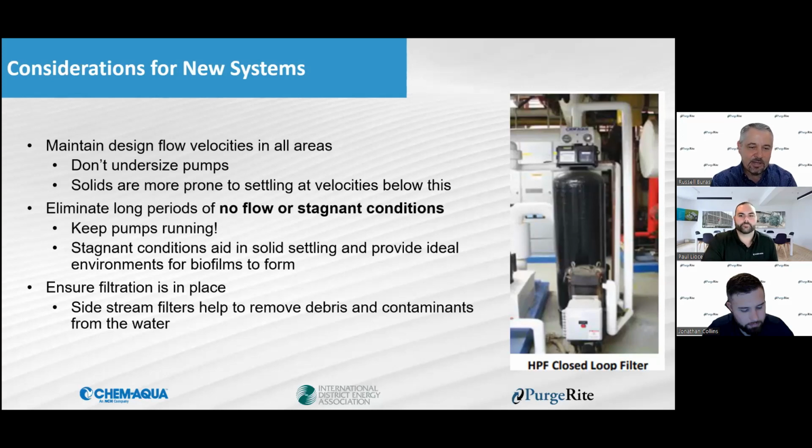And you kind of go back to how we talked about commissioning a system and laying up a system. You may want to think about what you're doing in your procedures and processes in your campus or the system that you're maintaining, because that can cause a problem. And you can have permanent side stream filtration and/or air dirt removers installed as well.